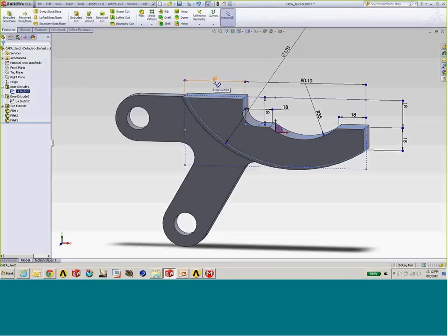One nice thing about SolidWorks is if you roll the mouse over a particular dimension, you can see the dimension name that's assigned to it. So for instance, this horizontal dimension here is D3. That's one that I won't be bringing across. Here's my jaw length. I've renamed it from its default designation to MP_jaw length, again, to fill out all parameters with an MP and to have a name that I'll recognize. Jaw height over here. The jaw outer diameter, we'll be bringing that across as well.